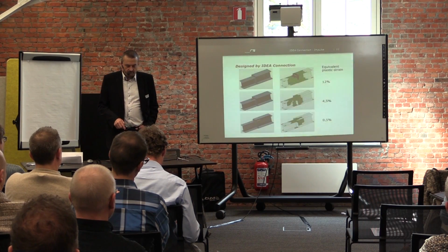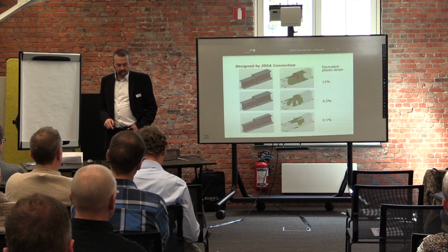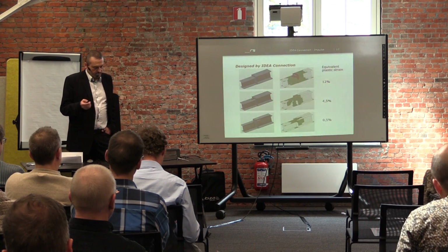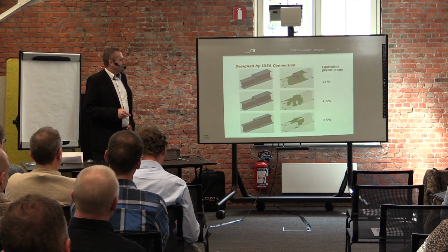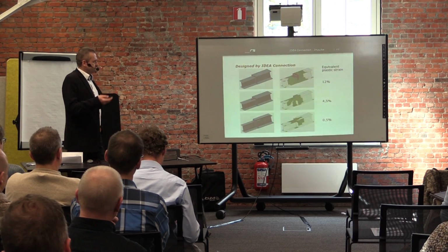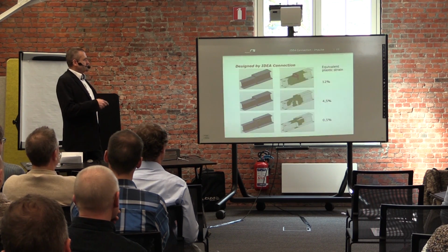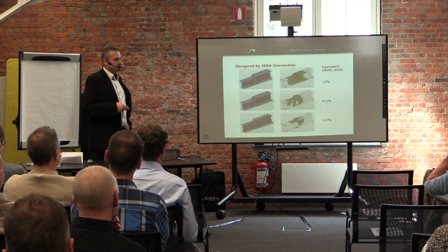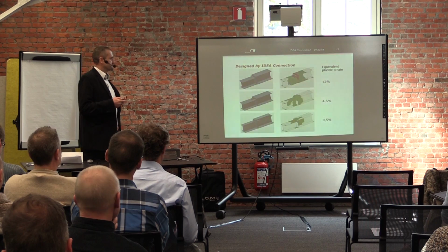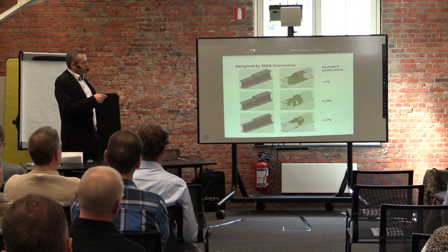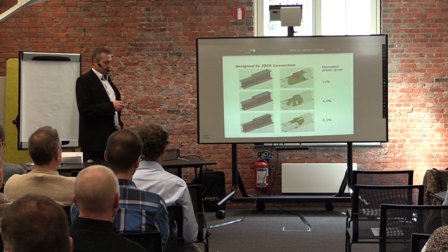And when we apply this plastic analysis or elastic plastic analysis, the results which we get are much more understandable, and we can see from them where the real problem in the connection is, and then we can do something with it.